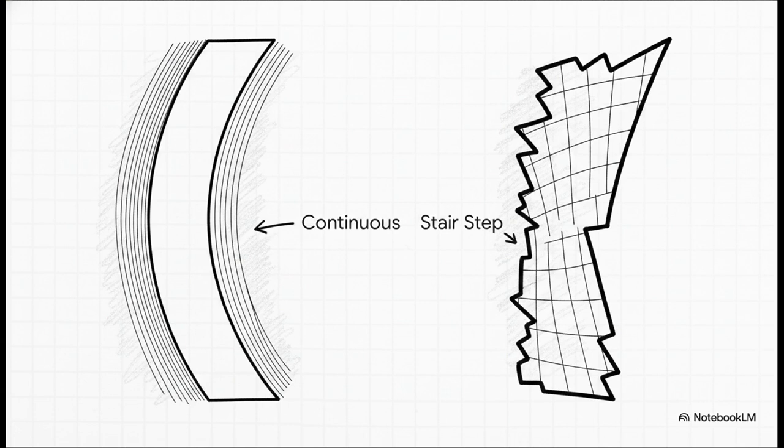To really understand why this matters, let's think about a golf ball. A golf ball has dimples that act as deliberate surface roughness. When the ball flies at a Reynolds number of about 10 to the 5th, which is right in the sweet spot, those dimples trigger an early transition from a smooth laminar boundary layer to a turbulent one. And to capture this critical boundary layer behavior in a simulation, we need highly precise mesh inflation layers, using tools to perfectly control the growth rate and sizing.